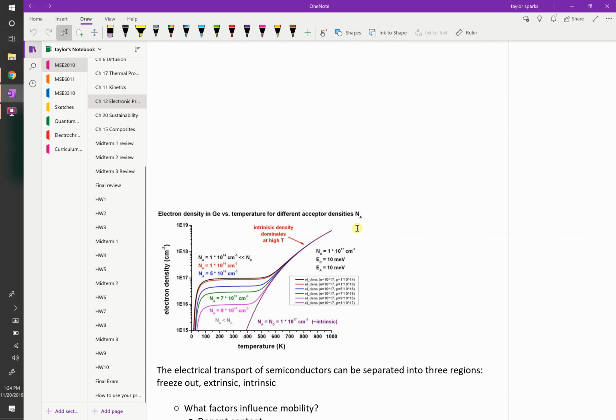It just takes a little bit of thermal energy, and you're in the extrinsic region. This is your extrinsic region, where depending on what level you're doped at, these represent 5 different dopant levels. This is a little, more, a lot, right? As you move this way, actually that's a little bit non-intuitive. You got to look here. In the intrinsic material, it's doped with 1e17, so it intrinsically has some carrier concentration.